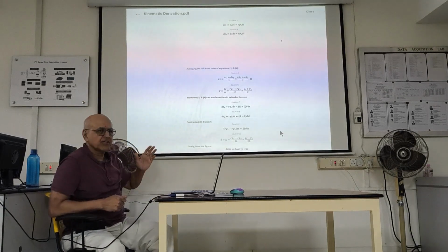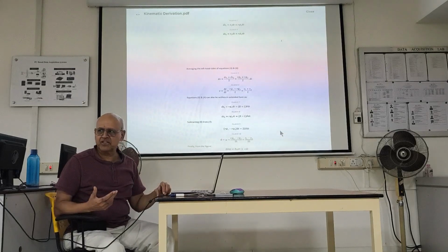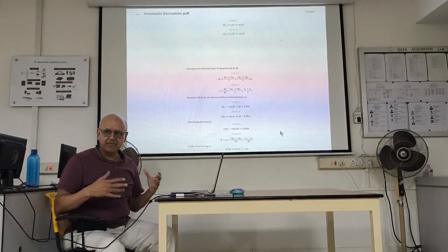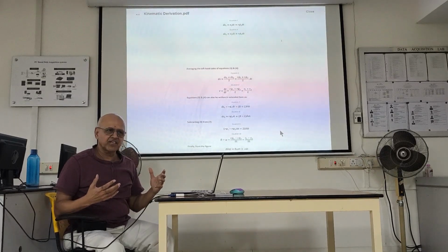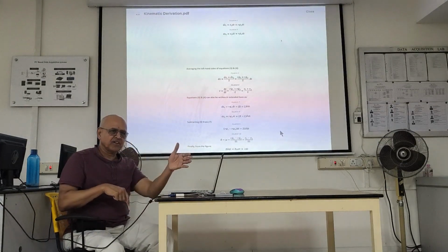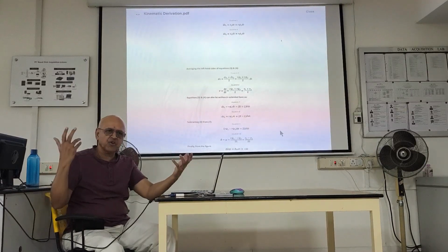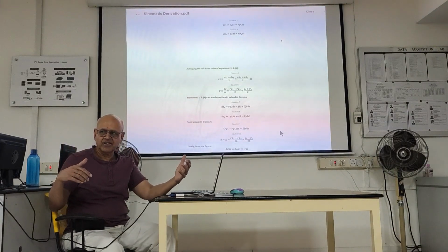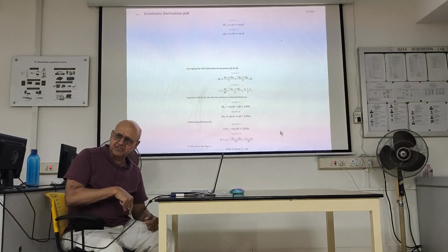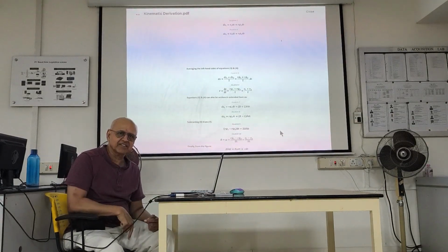Over here, the center of rotation is R this way or R this way. So when I'm just spinning, where is the center of rotation? Think about it. I'm not moving. Is the center of rotation directly below P? V left is 5 meters per second, V right is minus 5 meters per second. I have no velocity because it averages out to 0, but I'm spinning on the spot. So the center of rotation, the center of curvature of the circle, is right here, underneath. Does that make sense?